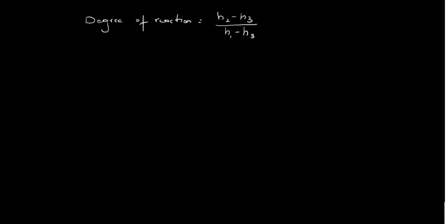Now we will try to write the expression for the fixed blade and the moving blade and for the total enthalpy line. Right? For the fixed blade, what would be the expression? Fixed blade, it is nothing but delta H is H1 minus H2. Why have I given H1 minus H2? Why can't I go for H2 minus H3?